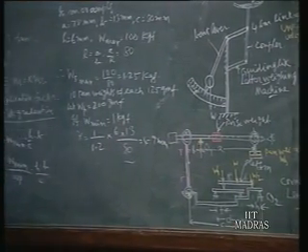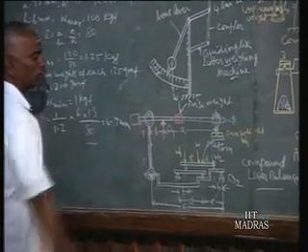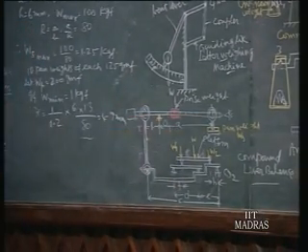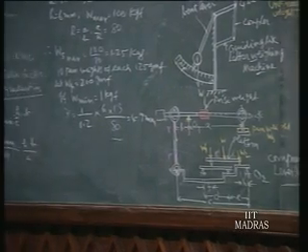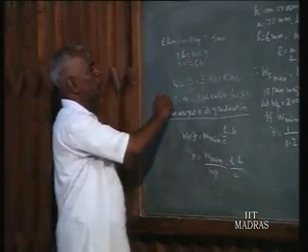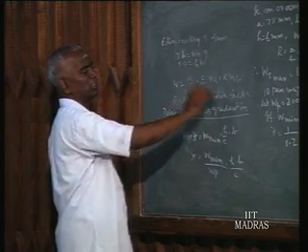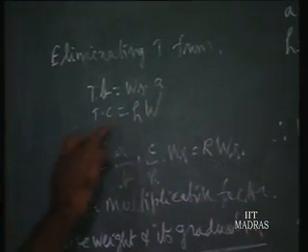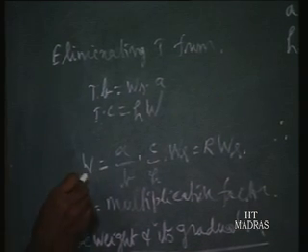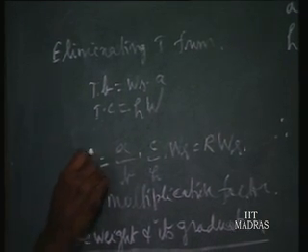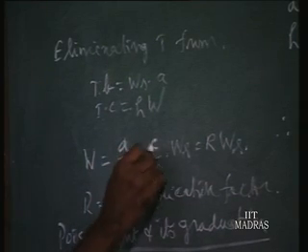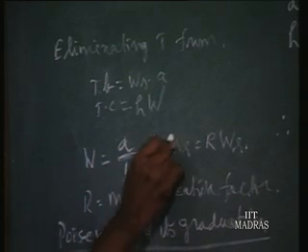For measuring a few tons of weight, we use only a few kilograms. So what is that multiplication factor? We obtain it by eliminating T from those two equations. T into B is Ws into A, we derived first. That is the first lever, and for the second lever, around O2 we have this equation. Eliminating T, the weight we measure is W equal to A by B into C by H into Ws.